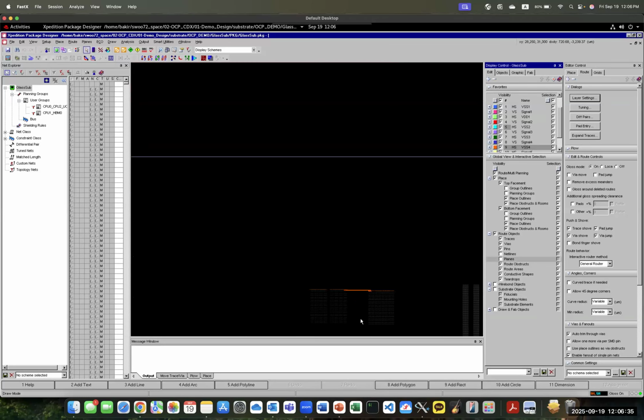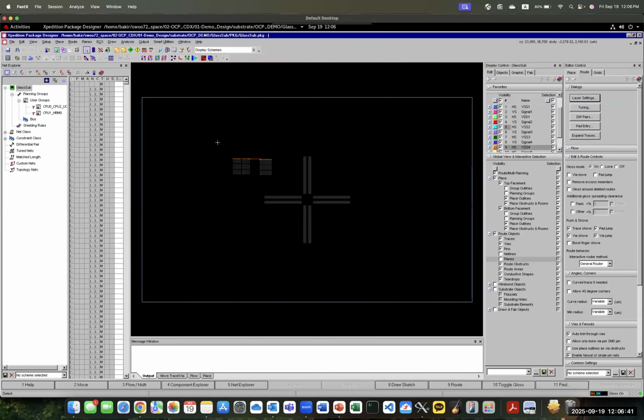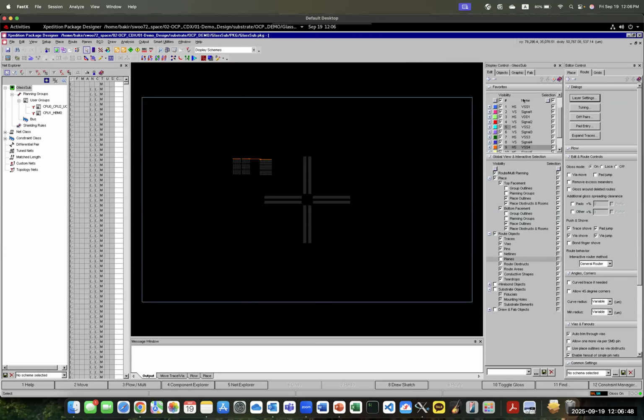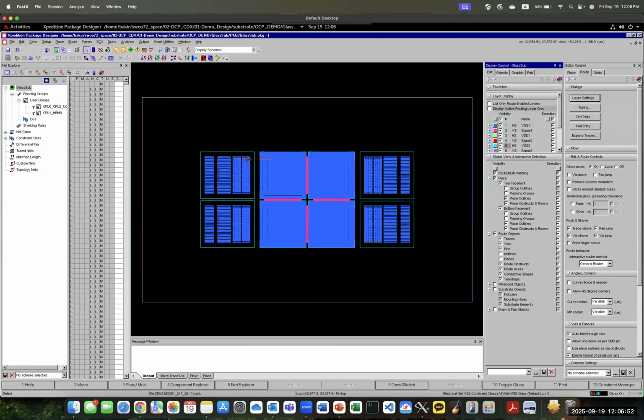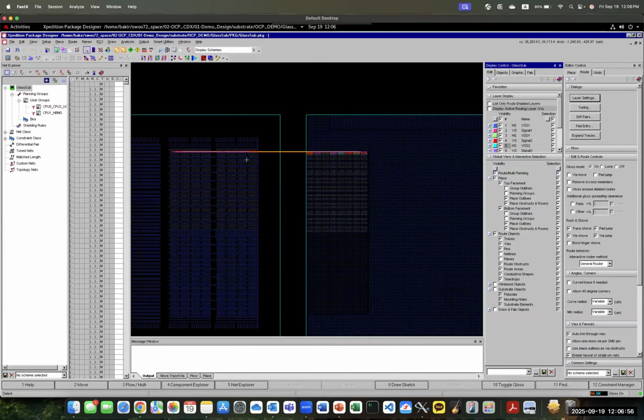This is to see what will actually work and what will not. Front to front is going to be the minimum length connection, and back to back is going to be the maximum length connection. That's going to give us a boundary for how the signal integrity looks, kind of worst case and best case.